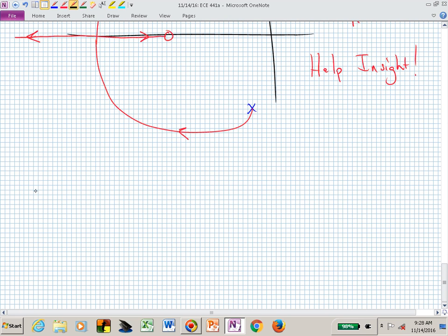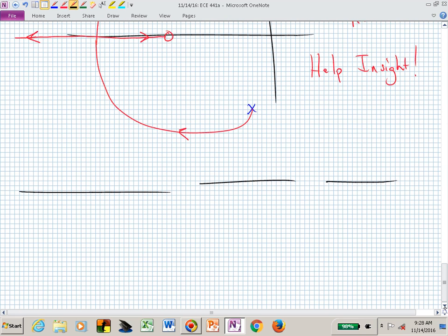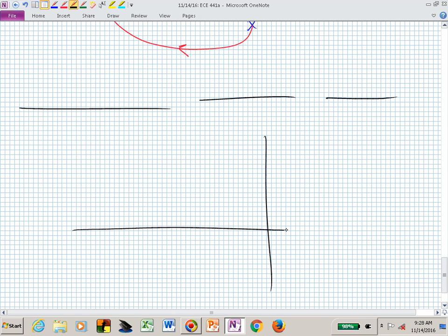So if we come back to reality a little bit with a phase lead controller, the phase lead controller says, oh, let's put a 0 and a pole. And we now are trying to determine where we want those. And we now have G sub C is K (s plus z sub c) over (s plus p sub c).